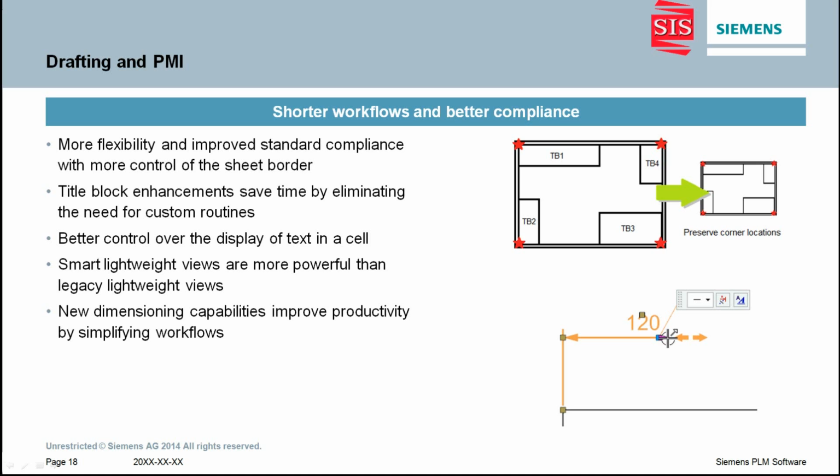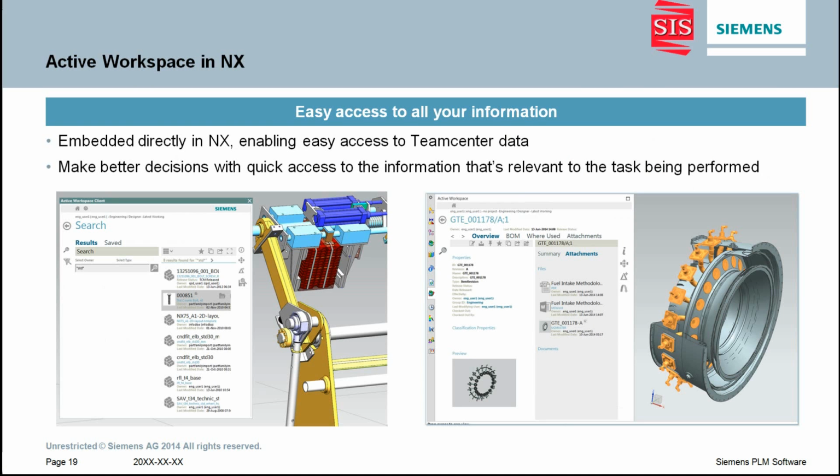NX 10 also has support for vertical text and dimension enhancements for a single-sided display of linear and angular dimensions, support for associative linear directional dimensions and feature size dimensions, support for reusing existing ordinate origins, and support for adding jogs to linear dimensions and extension lines.